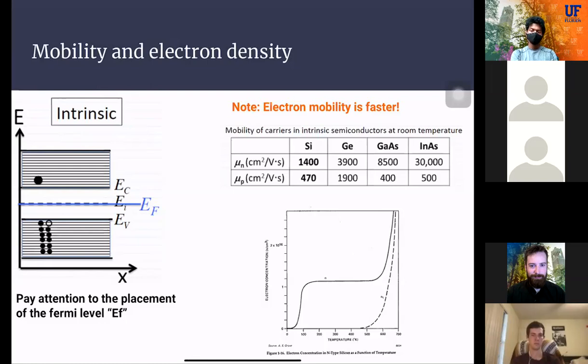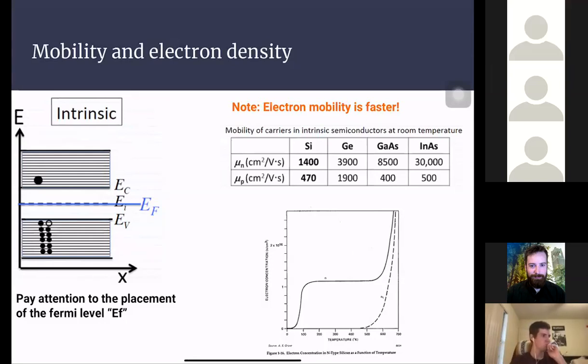The number of charge carriers increases from 0 Kelvin to about 100 Kelvin and 200 Kelvin, and in the range from 100 to about 500 Kelvin, it's kind of a flat line. That is really important because our room temperature, about 298 Kelvin, stands within this range, and this is the range in which semiconductors actually operate.